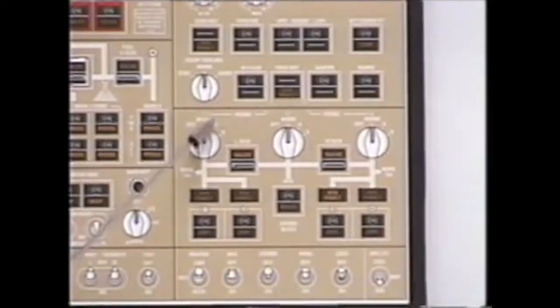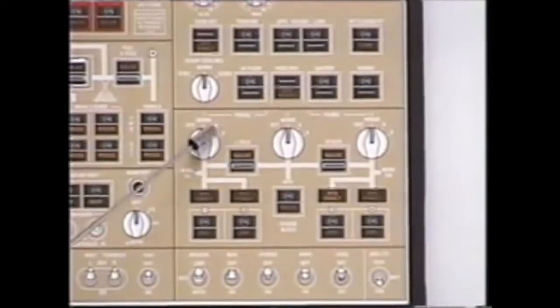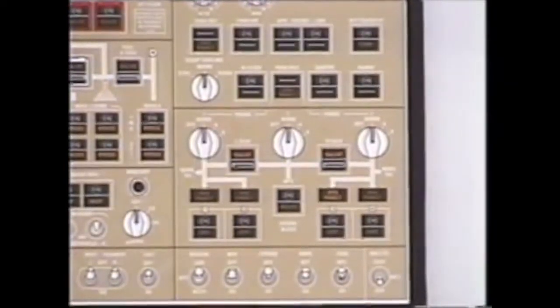Each pack has 2 controllers. There's an A controller and a B controller. The captain will reach up and select the normal position. The reason for this is because the system will use the opposite controller from what was used last flight. It alternates between the 2 controllers. To determine which controller is in use, bring up the ECS synoptic, and the controller in use will be indicated inside of the pack circle. If the selected controller fails, the other controller will automatically step in. If you are in a selected controller A or B and that controller fails, it again will use the other controller to step in.